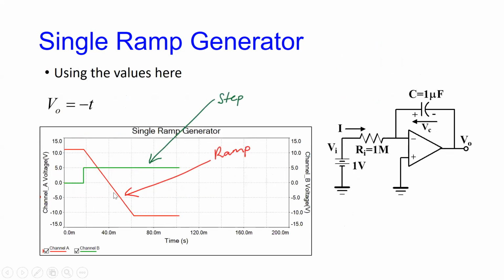So you could get this now. Whatever R and C is, you could get this ramp as short or as shallow as you want by picking the value of C and R. Usually for a typical op amp like a 741, this normally is about the maximum you could go for the input resistance, about a megohm. Here, you could probably get up to maybe 10 microfarads.